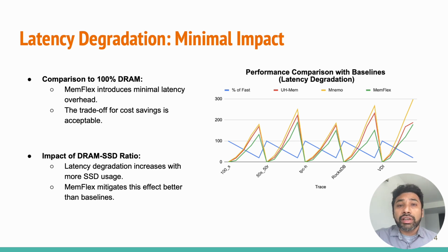Compared to a system with 100% DRAM, we see that MemFlex introduces minimal latency overhead. The trade-off between cost savings and latency is considered acceptable according to industry standards. While latency degradation increases with more SSD usage, MemFlex mitigates the effect better compared to the baseline techniques.